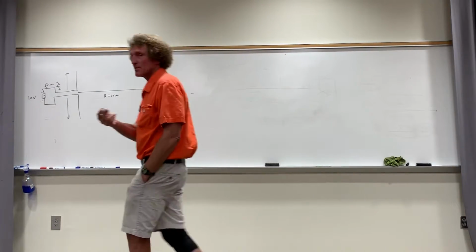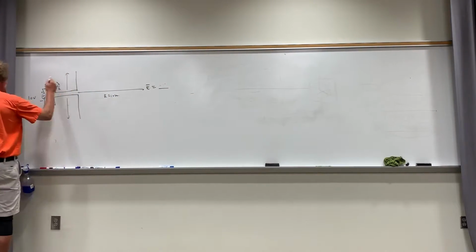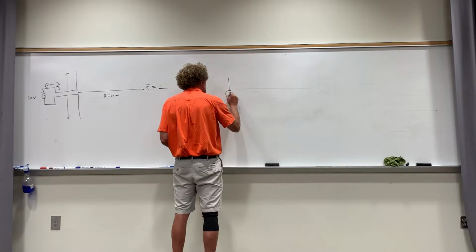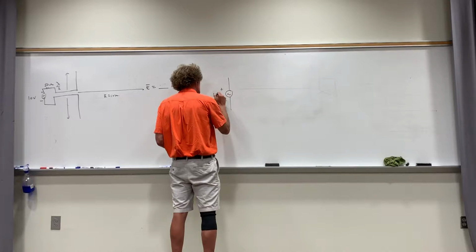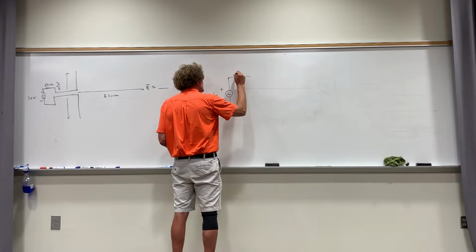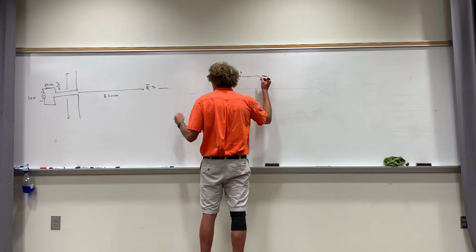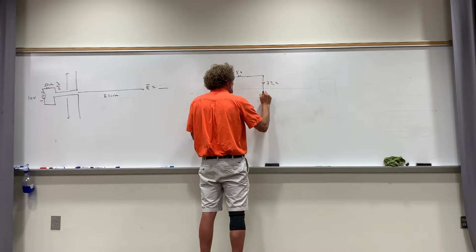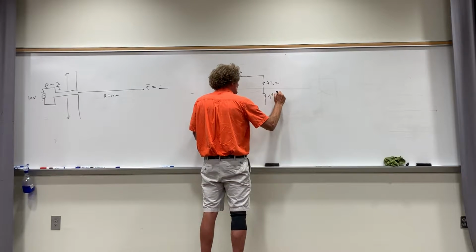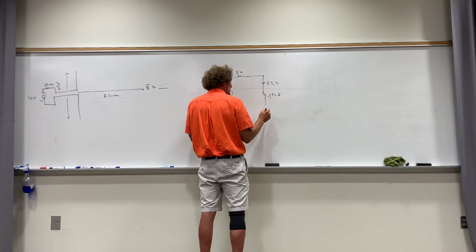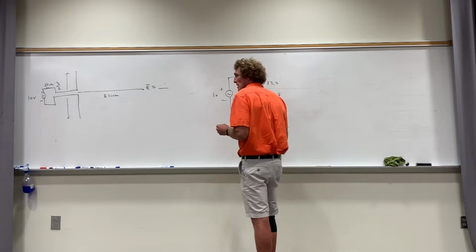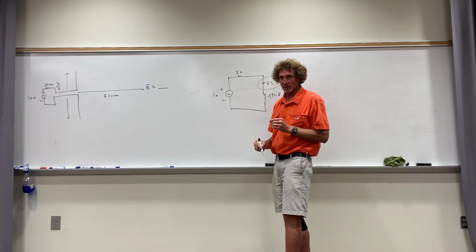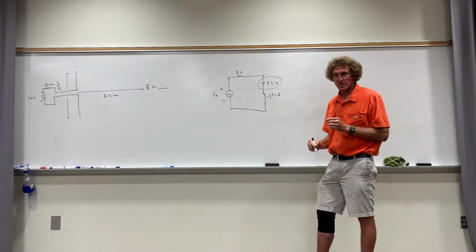By the way, here's how you would find power. First, you would represent this in terms of its lumped elements, and you would say the equivalent circuit is this. I have this voltage that's 10 volts peak, and then I have an internal resistance of 50 ohms, right? Now I put in the equivalent antenna circuit. That's equal to a real resistance of 73.2 plus j42.5 ohms, for a half-wave dipole cut down to 0.485 wavelength. So there's my circuit. Now all the radiated power is associated with the power that's going to be absorbed by that element right there. Can everybody follow me on this, class?